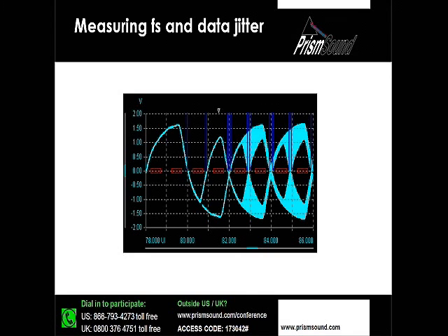So what I'd like to do is explain how we go about, and actually you could as well, to determine whether you've got clock or data jitter or both. So if we look inside the preamble, if you remember the preamble, and the parity bit allowed for the same transition in the preamble, and as a result, if we look inside the preamble where there is no audio data, and we measure the width at the zero cross, that will give us the clock jitter.